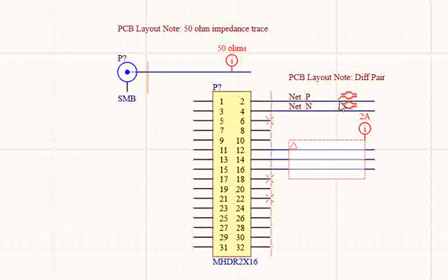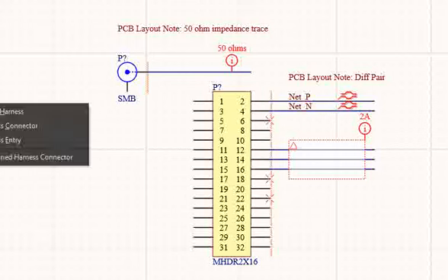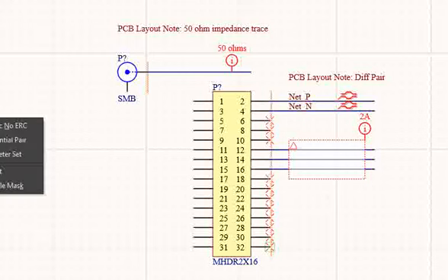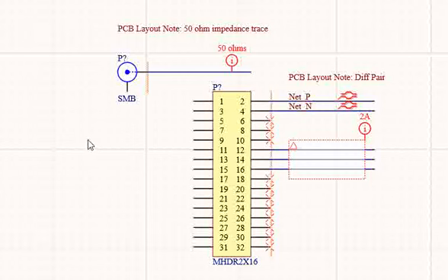Like here, if you see, we only have 3 pins, right? In this case, if we want to have all these pins not coming under an ERC error, we have to place a no ERC directive, which is called a generic no ERC in Altium.